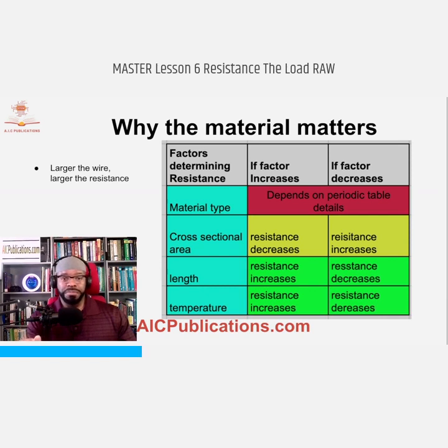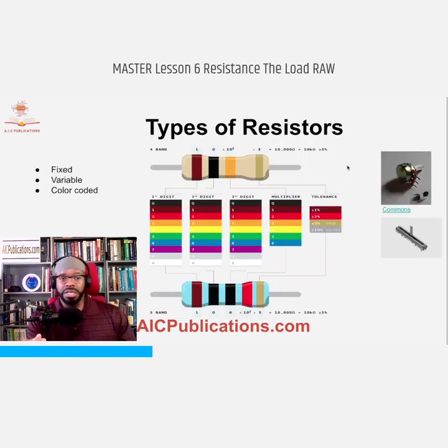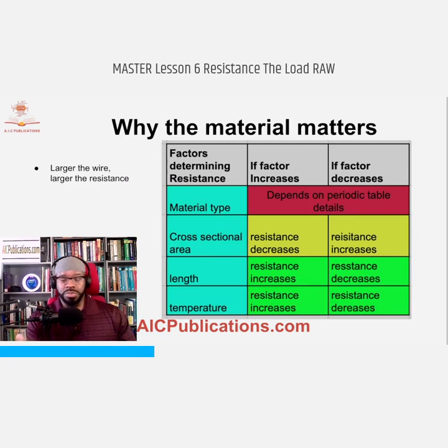Now, what you're looking at here is a list of standard wire sizes according to the American wire gauge. Notice that as the gauge number increases, so too does the resistance. However, as the gauge number increases, the diameter of the conductor decreases. This means that the greater the wire number, the greater the resistance. Or one could say that the smaller the wire, the larger the resistance.